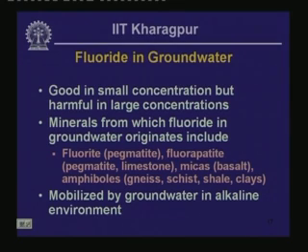So, if the local geochemistry is alkaline, or the pH level is above neutral, more than 7, then the fluoride in the rock or soil gets mobilized and carried with groundwater. And if there is a water well installed within such an aquifer, the water that is going to be drawn, if ingested, is going to cause the health problems that are related to elevated fluoride level, such as fluorosis.